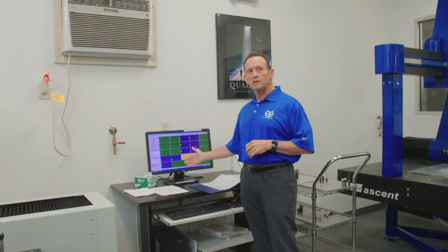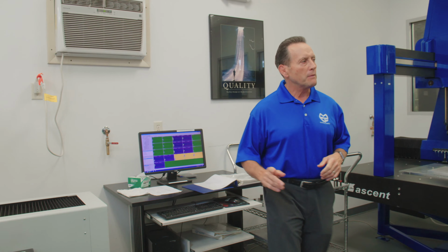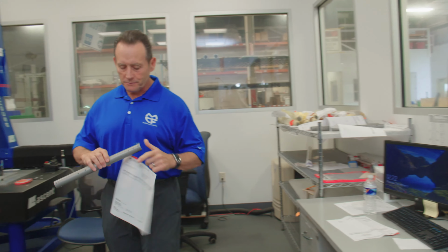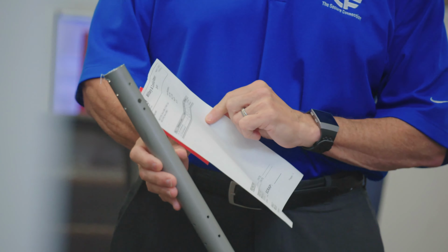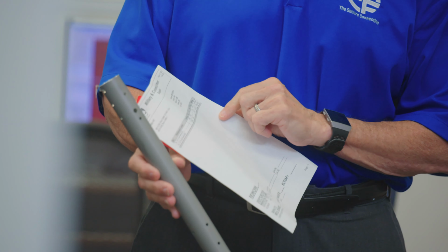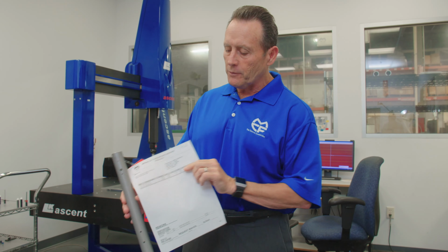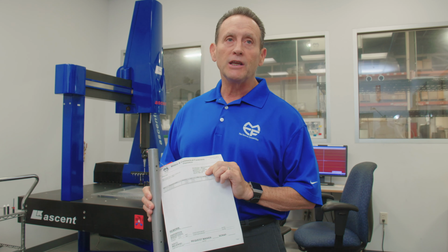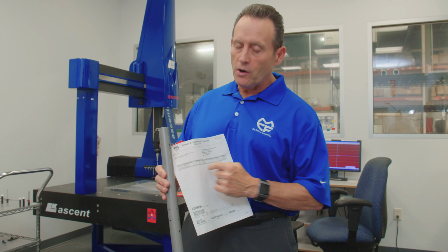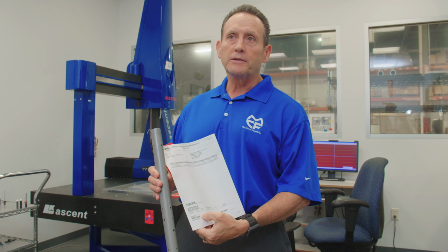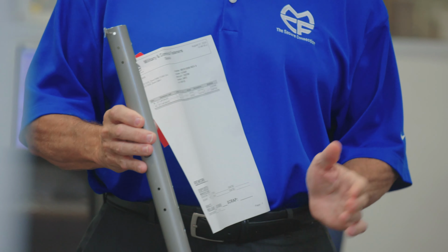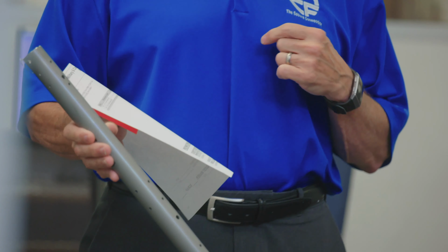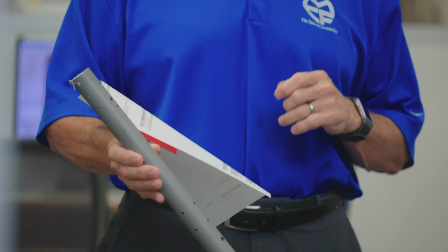If a non-conforming condition is detected, the part is then identified and labeled. See here we have a disposition request. In here you'll see we have the material lot number, the part lot number, and the sequence number, and also the non-conforming condition. It will sit in here until it's dispositioned. It could be dispositioned to scrap or to rework. That's the only disposition authority allowed out here in manufacturing.